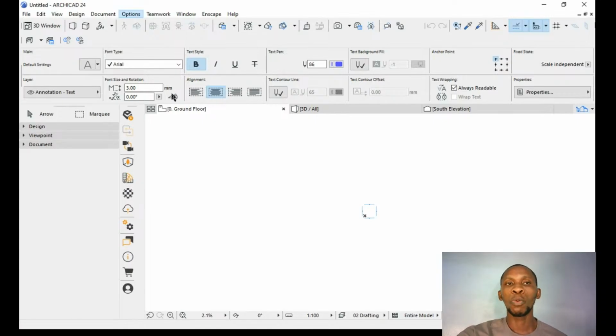And then we have project preferences. On that, I mentioned the first thing we want to check is the scale of the drawing they are doing it in. The second thing you want to check is the pen width, pens and colors, right? The third thing is the working units, right? Are you working in millimeters or meters or centimeters or feet or inches, whatever units you want to work with?